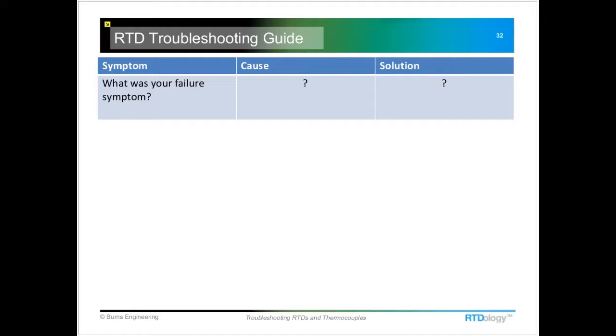Yeah. We've got another couple more questions here. Another question: what would cause a thermocouple to read correctly at 250 F, then suddenly step down to an incorrect reading by 50 degrees F, then 24 hours later jump back to the correct reading in another step change? Wow. Yeah, I've actually heard of something similar to this. I would suspect that there's some machinery or something that's starting up in the facility on a regular schedule, and then it's causing it to change like that.